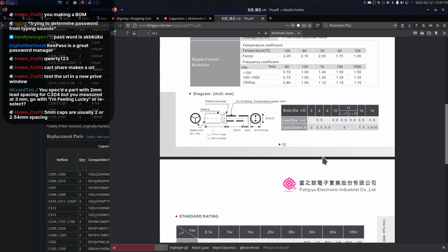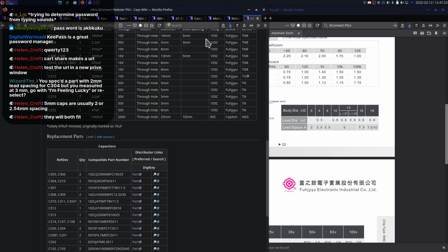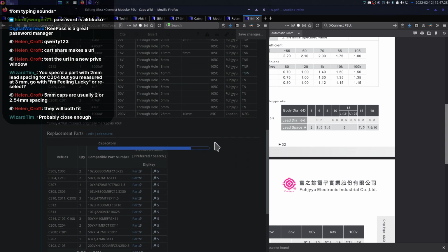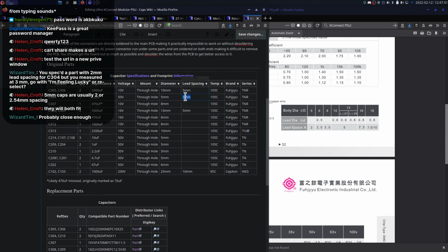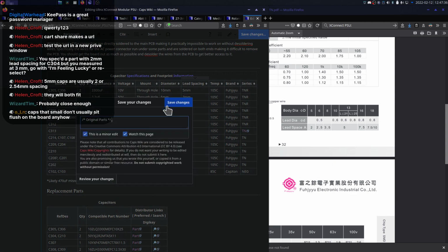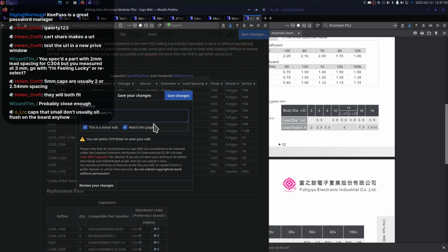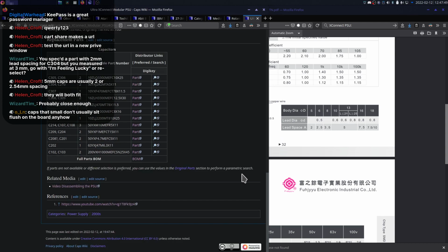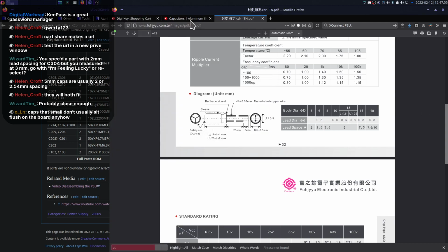Okay, so I must have measured wrong. So it's probably fine then. I should update this. Edit. Worst case, it pokes up slightly, but I bet it's 2 here, and I'm just an idiot, because the datasheet says it's 2. Fix lead pitch. Yeah, they're usually weird, because they've got like a weird hourglass type thing going on with the leads, so...